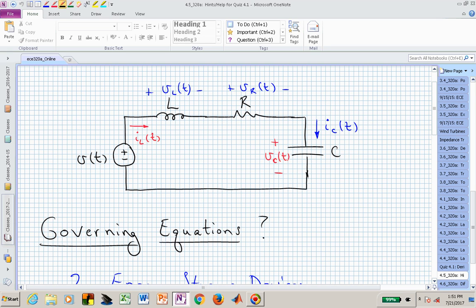That's an instantaneous relationship between voltage and current. The voltage and current relationships on L and C, however, do have this time connection by means of a first-order derivative relating the current and voltage in the inductor and capacitor, and that's what gives them this introduction of dynamics into your system of equations.